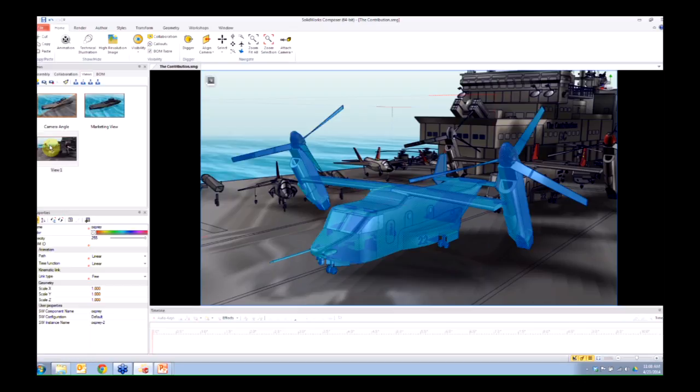So in a view, if you take an object from point A to point B, it's going to translate it along a linear path between those 2 points. If you want to rotate something 360 degrees, you can't, because it wouldn't even move. View A would say it's located here, view B would say it's also located here, so then nothing happens. So if you wanted to spin that 360 degrees or more, then you have to do that in the animation. And that's what we'll be doing here.